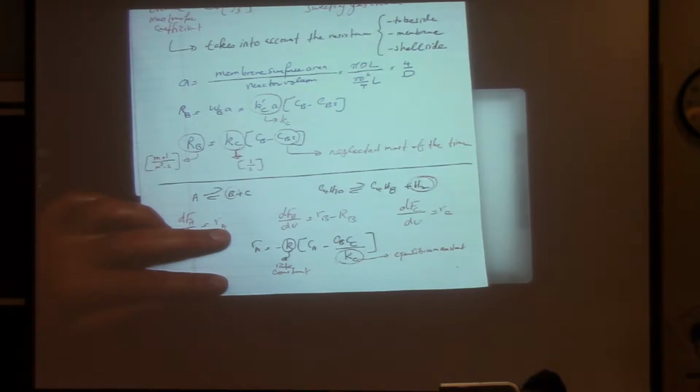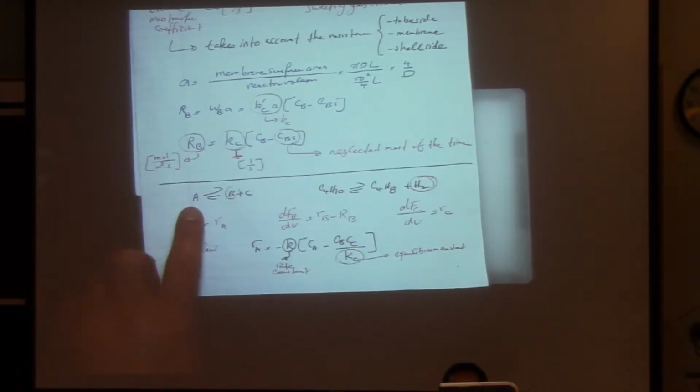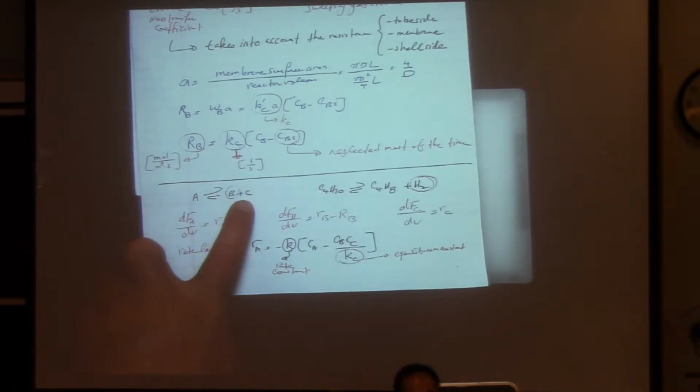Okay, so this is your rate law. And if you remember, because you are dealing with a few rates, A, B, C, you need to have a relationship between RA, RB, RC, which you can derive from the stoichiometry. So basically your minus RA is equal to plus RB is going to be equal to RC. So then you need all these equations.